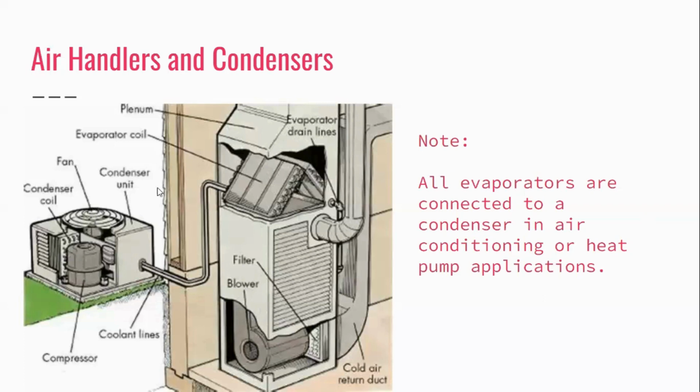But this is typically what we see. So we've got our condensing unit, which again has a fan, condenser coil, and compressor. You'll have filter dryers or sight glasses, not on AC, but you'll have other little components in there, but they don't matter. They're not enough to wreck the system. Other than, I'm glad that there is a filter dryer here because when we're talking about restrictions, it's not always the TXV, regardless of what every HVAC tech in the world tells you. It is not, in fact, always the TXV.